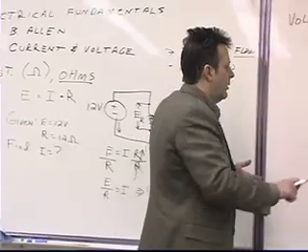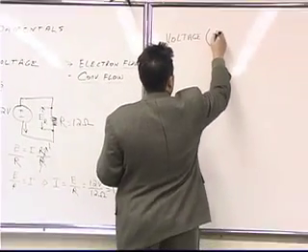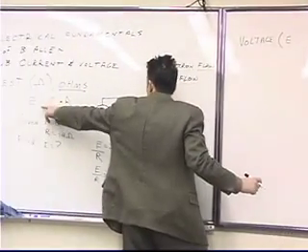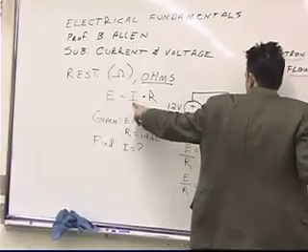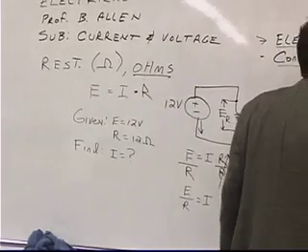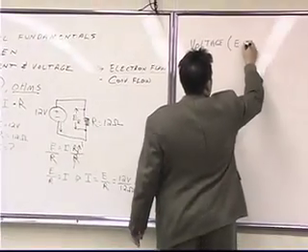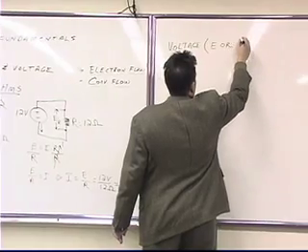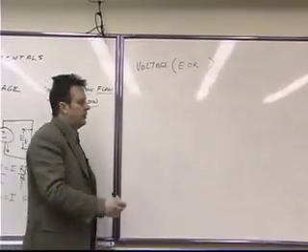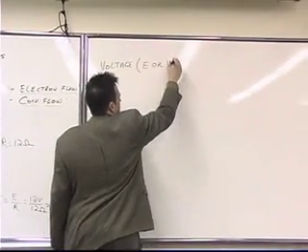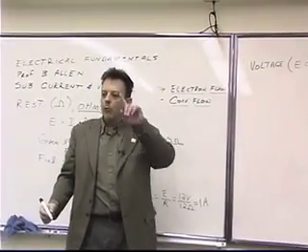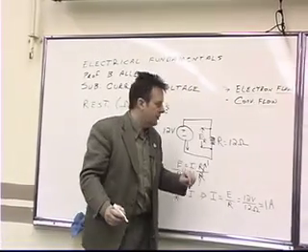The two letters used to describe voltage are E, which we saw in our formula, voltage equals current times resistance. That's the simplest formula for Ohm's law. The other letter that's used to describe voltage is simply V. So some books will write Ohm's law like this.